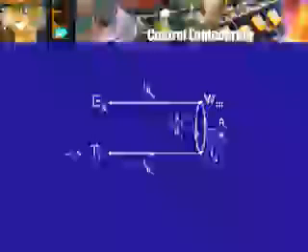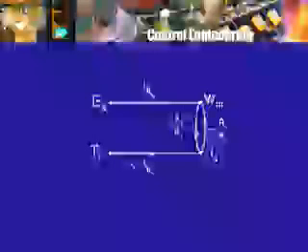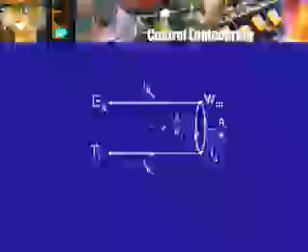This equation is for node Ia, Ia equal to 1 by Kt TL. So, I put one more node TL. Here is the edge from TL to Ia, its transmittance is 1 by Kt, that is okay. And then I have the other edge from omega m, Kf by Kt.